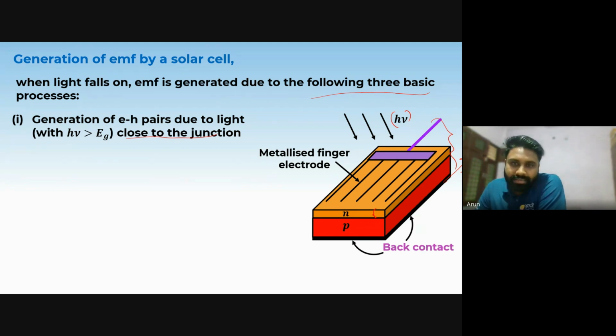The electron generated in the n region has absorbed the photon, so its energy increases and it wants to cross the depletion region. If the n region is too large, it will go to the junction but will not cross it, because most of its energy is used to cross this n region. So that is why we have kept this n region very thin.